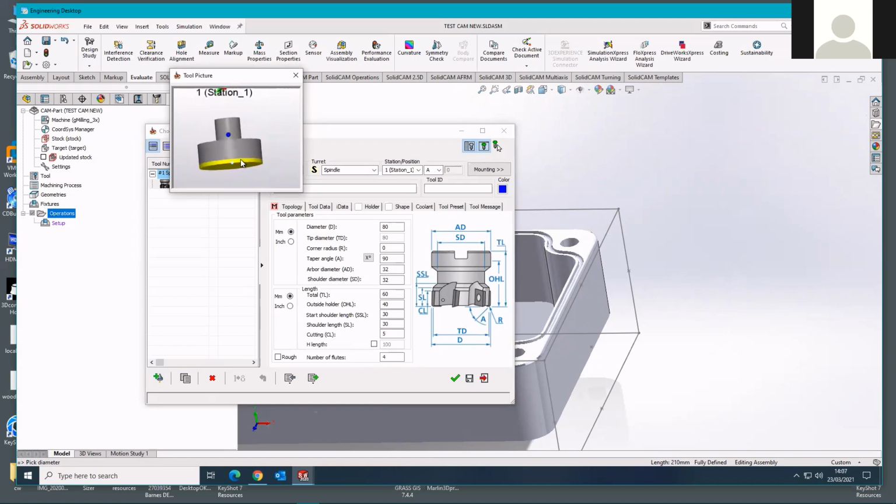So that's going to tell us if we try and cut 6mm and bring this tool into a block of material that's 6mm deep, the system should flag that and say, whoa, whoa, whoa, you've just hit the material with the tool where there's no cutting face, and you've arguably broken the tool or damaged your stock material or damaged the CNC machine.